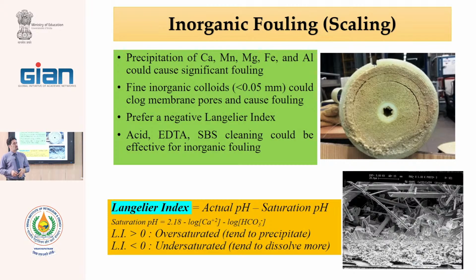But we do not reduce the pH that much because reducing the pH causes corrosion to increase in the pump. And also the acid can destroy the membranes, the polymers. Therefore, we only reduce it by a very low amount to decrease the sedimentation possibility.